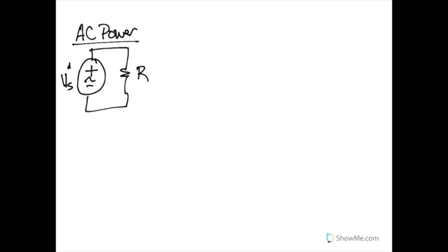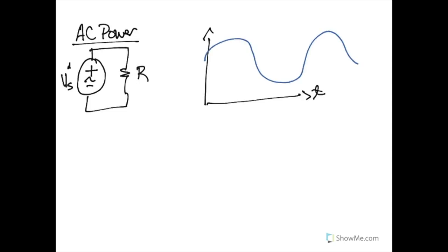And imagine that we had put this circuit in our simulator and we want to see a plot of both the voltage and current across the resistor over time. So, for example, here, let's say that our blue line is our voltage over time. And maybe this had a peak of 5 volts. And then because of the resistor, if it has a peak of 5 volts and our resistor is 5 ohms, then we will have 1 amp of current also flowing through at the same time.